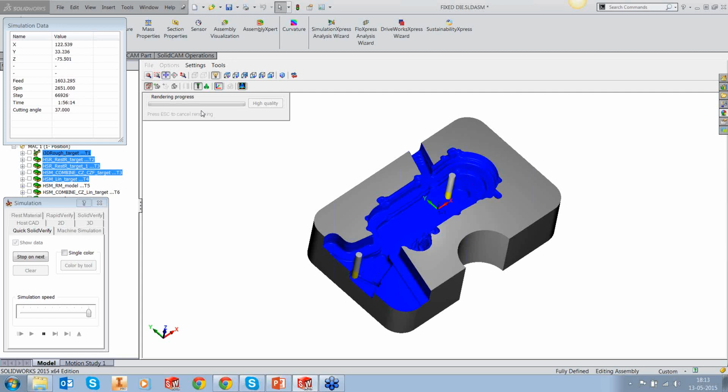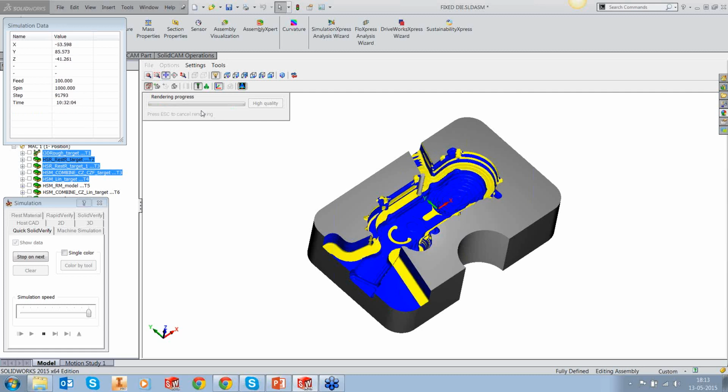This is true even if you're doing a small part, because the principle of machining is constant cutting at every point. If you have material that's more in some areas and less in some areas, the load that comes on the tool is not uniform. So you will end up blunting the tool or reducing the tool life and also compromising on the surface quality.